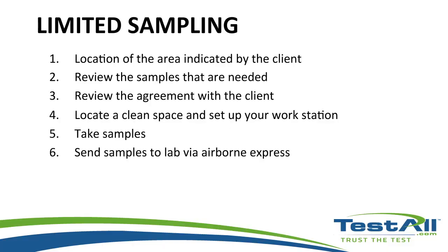Let's look at the limited sampling and the steps involved in limited mold sampling. First one is the location to be identified by the client. Second part is review the samples that are needed to be taken with the client. Then you put it on the agreement form, review the form with the client, and have them sign off on it. From there, locate a clean workstation, sometimes a kitchen counter. Sometimes if the house is a mess throughout, then you're going to be using your vehicle, so make sure your vehicle is a clean area.